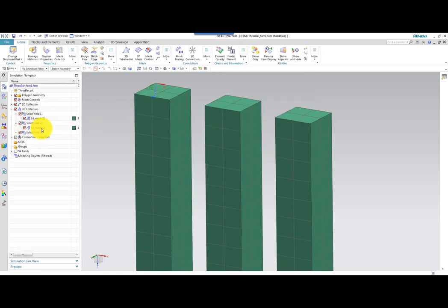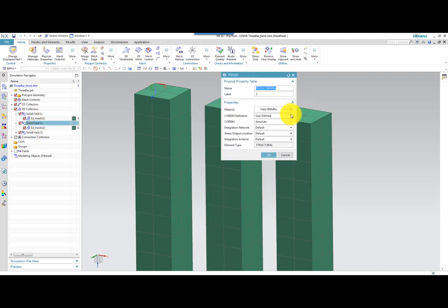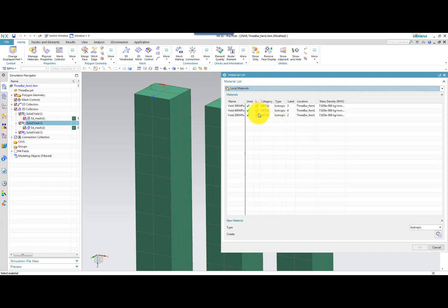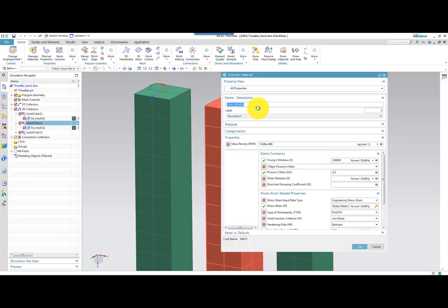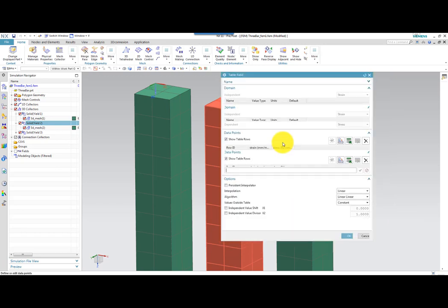And then for beam number 2, I used yield number 2 properties, and we can have a look at them as well. That's the 300 megapascal yield stress. It's the same E modulus, the same Poisson ratio. I use engineering stress strain, and I can have a look at the properties. It's 0.0, and the yield point is 300 megapascal, and if I divide it by the E modulus, which is the same for all beams, I get this strain, 0.0015.